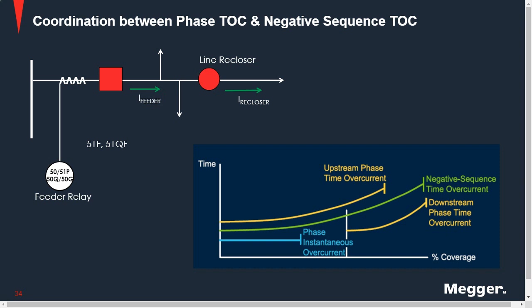And of course, we do like to. It makes it much easier to be able to isolate an element, which is why I bring up testing on a spare output, especially if you're troubleshooting. Testing using a spare output and just isolating that single element to test.